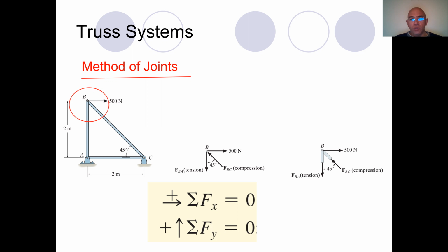Now, certainly what we do is we write the force equilibrium in a joint. Now, if we isolate each member and assuming that regardless of the type of joint at point B, it can be welded, it can be bolt jointed, it can be riveted, or whatever it is, doesn't matter. We assume that it is pinned at point B in method of joints.